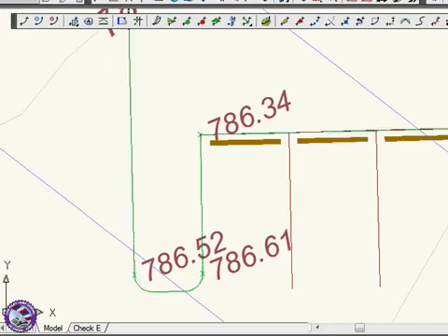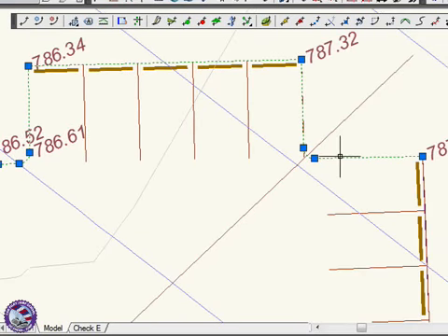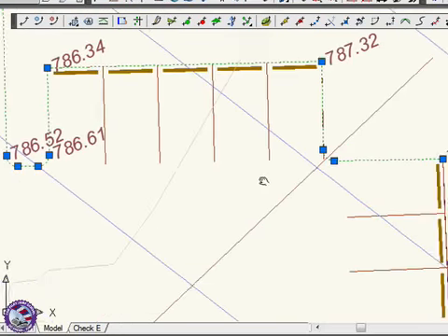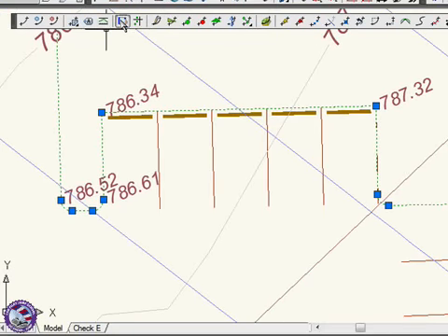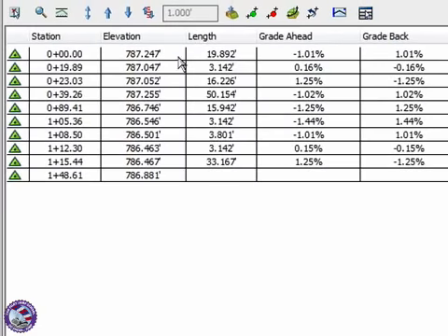And I end up with, it converts, goes to my road line layer, but still looks like a grading line. Okay, so this is once again style driven. It has a whole bunch of points, and you will see it pulls out the elevations based on those locations. And so now I have an editable beast. I can turn it on and off if I have those intermediate points and you pulled them. This will actually show the grade breaks. I can move this up and down by default.